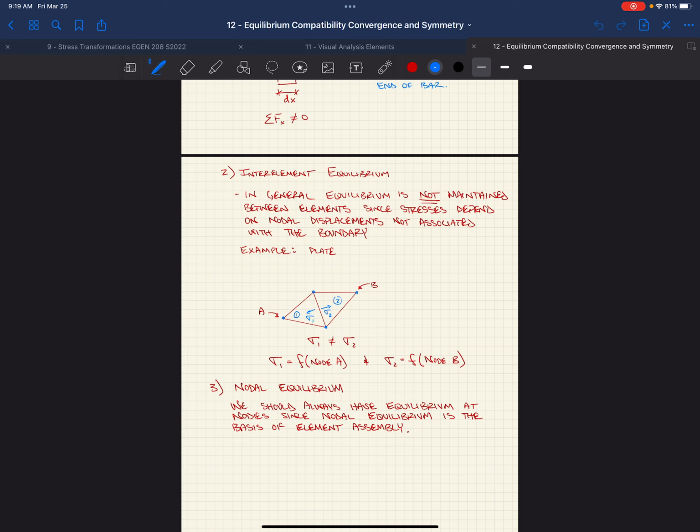and so you get this jump, right? And we know when we looked at the first homework assignment, we were looking at that axial loaded concrete column, right? We want to get convergence eventually, which we're going to talk about. And so we make those elements smaller and smaller and smaller, right? Which makes the jump smaller and smaller and smaller. That would be the hope, that we essentially discretize the model sufficiently enough that this inter-element equilibrium violation is very small. But we're not going to have equilibrium, right?